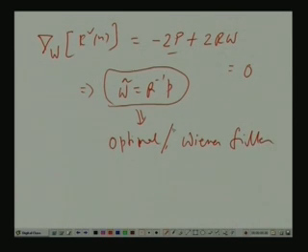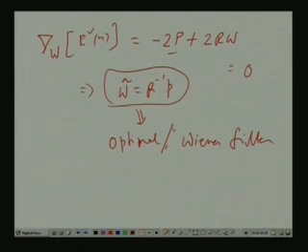In practice, if you know R and P, fine, you can calculate this R inverse P, but the problem is R and P are not always known. In that case, you have to supply this information externally. What do you do? This actually gives rise to the interesting case of the adaptive filter. When R and P are not known, or when the input statistics or the joint statistics between d(n) and x(n) change from time to time, you cannot have one filter designed once for all.